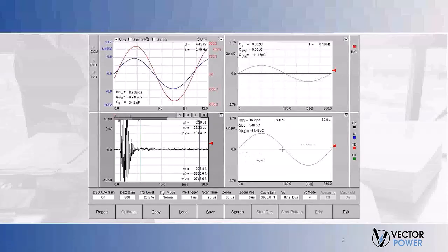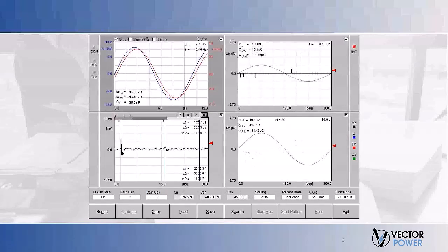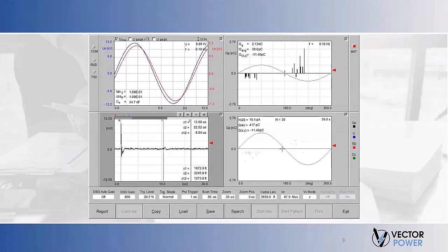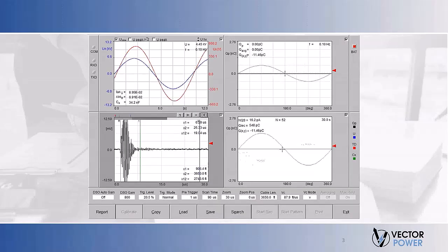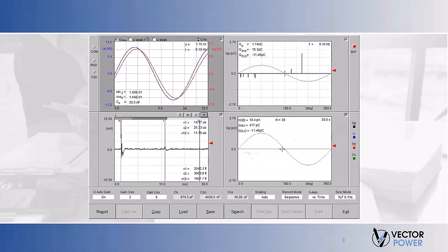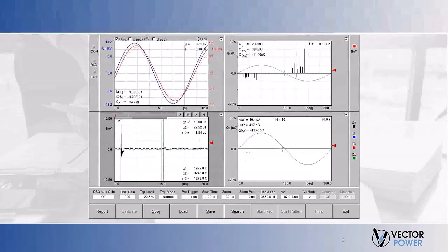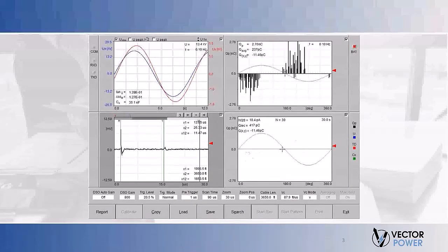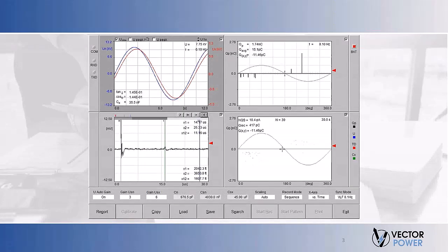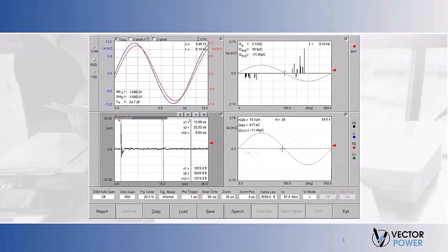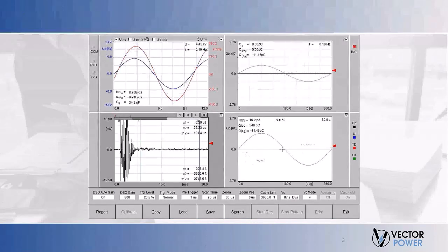The potential damage caused by partial discharge varies significantly. It could be negligible in some cases, while in others, it may lead to failure within seconds or over several years. Advancements in digital electrical measurement technology, both in the time domain and frequency domain, have enhanced the effectiveness of PD measurements.